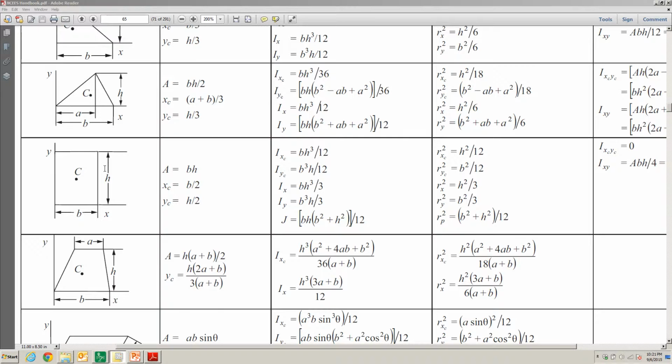We need to keep in mind that this is the top projection of our rectangular gate. So B represents the 6 meters of the width of the gate, equal to what we called W before, which was 6 meters. And the height is going to be the 3 meters divided by the sine of 45 degrees.